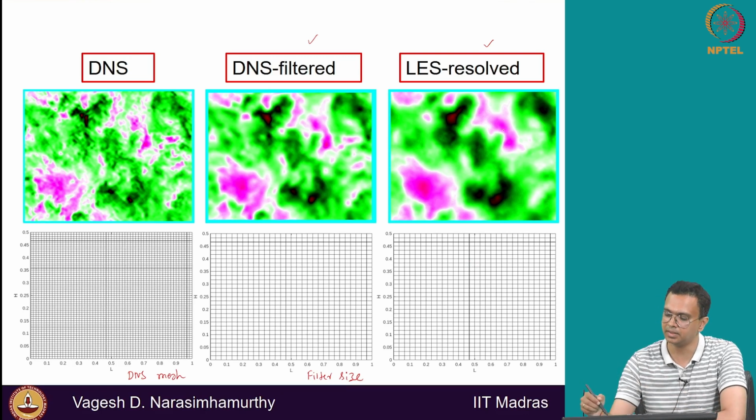That model error has resulted in some loss of information in this graph in the LES. But in DNS, the same mesh is used to volume average the data, and since the residue is exact, that modeling error is not there. There is still no loss of that information.